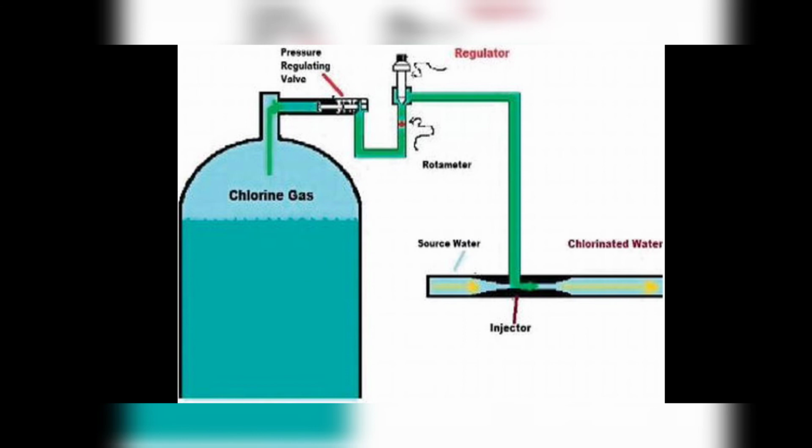Water plants monitor the chlorine levels continuously and very carefully in the treated water. They must add enough chlorine to ensure thorough disinfection of the water but avoid adding excess that can cause taste and odor problems when delivered to the customer.